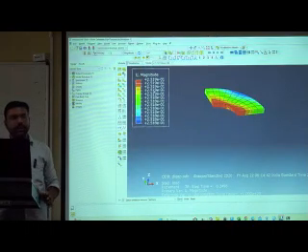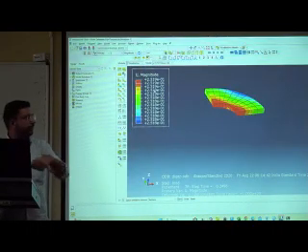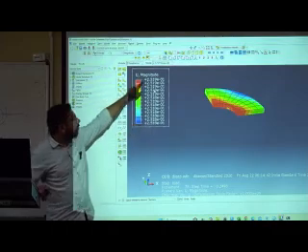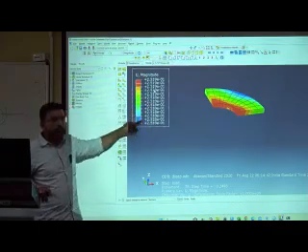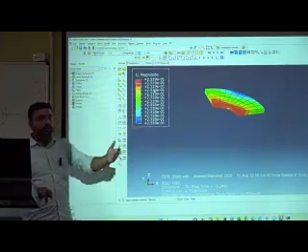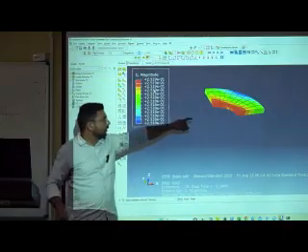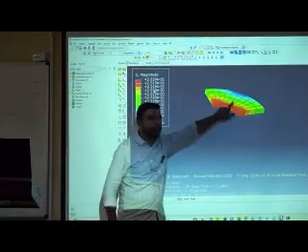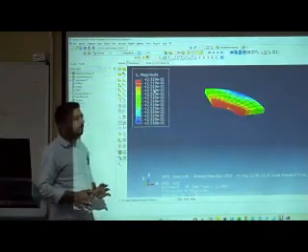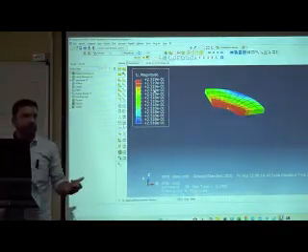So you can see that this is the prescribed displacement result. So the U magnitude is almost the same. It means it is not showing the differential settlement in the raft. So the settlement in this part and this part is almost the same. Very negligible difference is there.